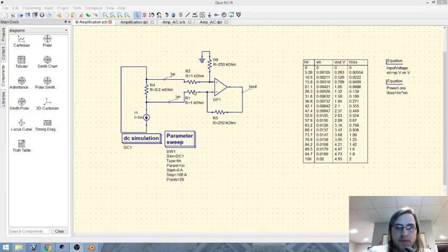These 4 resistors here set our gain, and we can actually look at it. We remember that our gain is this resistor over this resistor, and assuming that this resistor equals this resistor and this resistor equals this one, all we have to do is look at the bottom 2, and our gain is R5 over R1, so that's 250 kiloohms over 1 kiloohm, so our gain is 250.